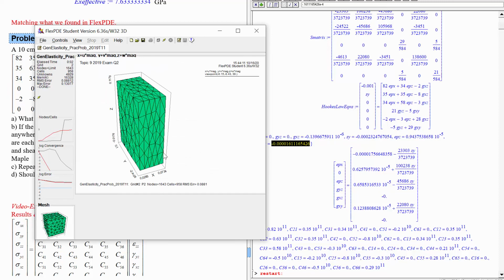Let's think about what's going on here. We said you can't move in Y. You're fixed to the value you had in Y, and we're going to put a stress in X and Z. That led to it needing to shear in X and Z because of how the material couples things. But that's fine. It didn't try to shear in Y, so we're okay.